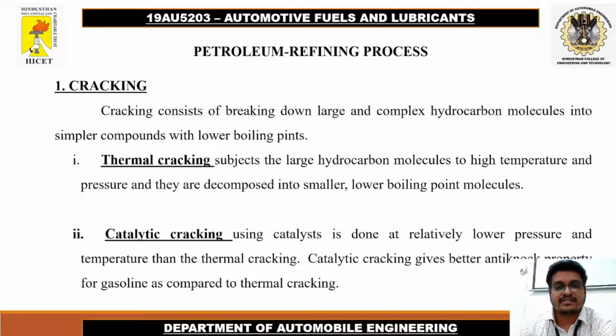Thermal cracking subjects large hydrocarbon molecules to high temperature and pressure, and they are decomposed into smaller, lower boiling point molecules. But in catalytic cracking, we use a catalyst to speed up the reaction, but it does not take part in the reaction. It uses the catalyst at relatively lower pressure and temperature than thermal cracking. It gives better anti-knock properties for gasoline as compared to thermal cracking.